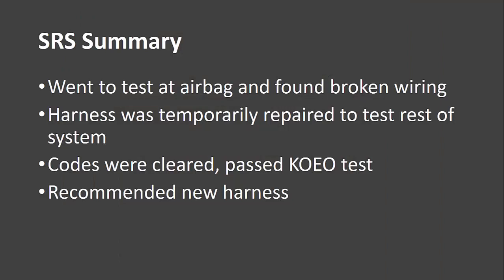So this is a good starting point. What we're going to do is repair the wire. Now, full disclaimer, I repaired the wire just for testing purposes. Most manufacturers do not want you repairing airbag, ABS wiring, stuff like that. So what I did is I just connected it back together, but then recommended the shop put a harness on